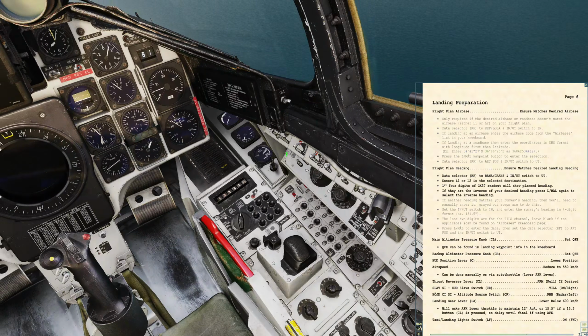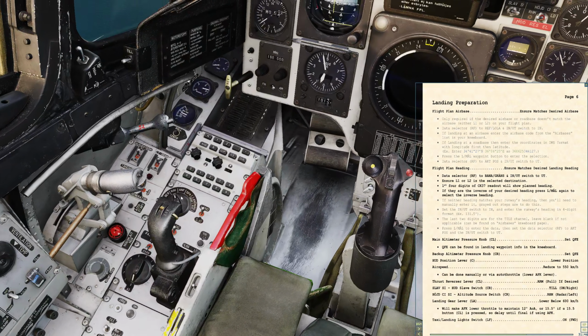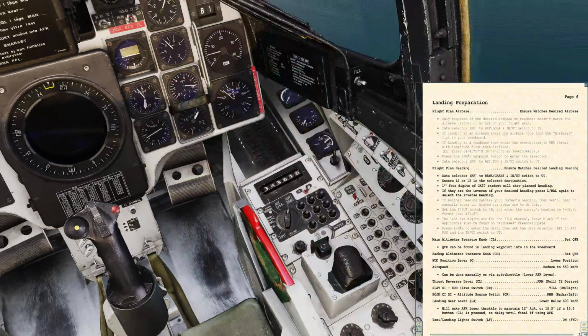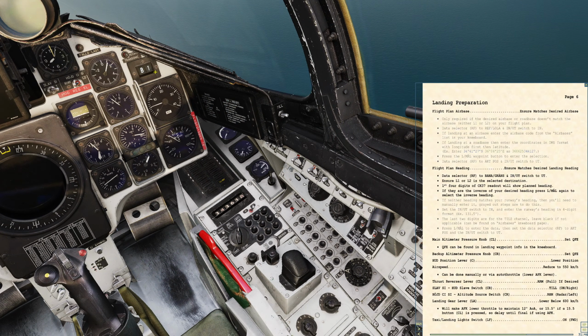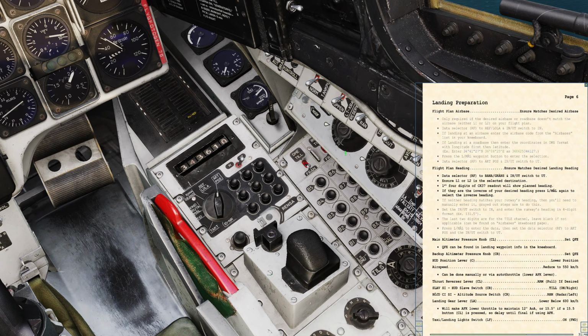Next thing we're going to do is we're going to select the landing airfield. So with actual position selected on the computer and navigation master mode selected on the left console, you can see here that currently I've got waypoint 1 selected. If I press the L-MAL button, that will then switch between landing field 1 or my alternate of landing field 2. In this case I want landing field 1, however I happen to know that this is wrong. The L1 position that I have today is incorrect. So how do we fix that?